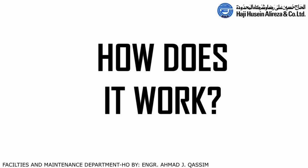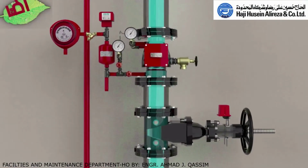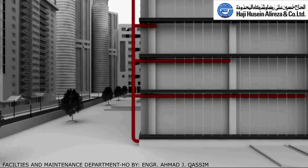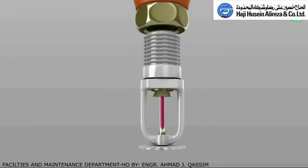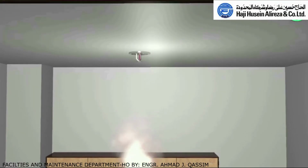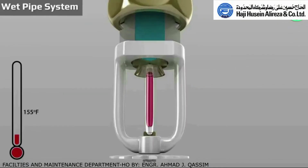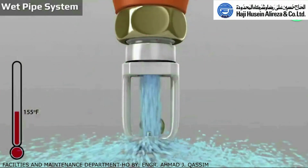How does it work? An automatic fire sprinkler system commonly uses water as the extinguishing agent, wherein the fire pumps will start to work when a sprinkler is set off. Most sprinkler heads feature a glass bulb filled with a glycerin-based liquid. This liquid expands when it comes in contact with air heated to its designed temperature. When the liquid expands, it shatters its glass confines, and the sprinkler head activates.